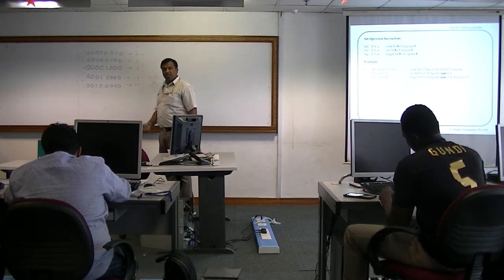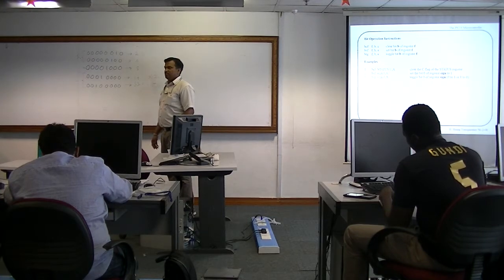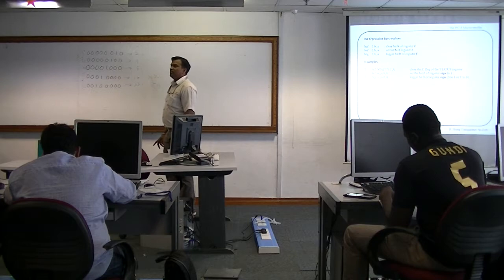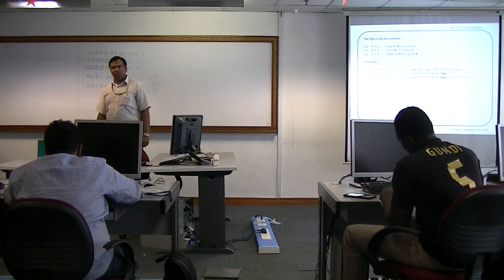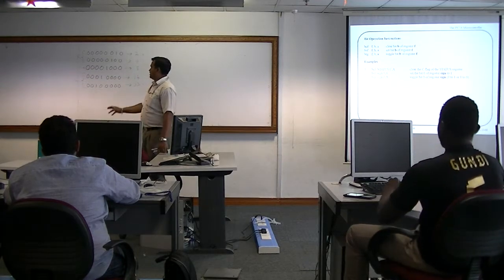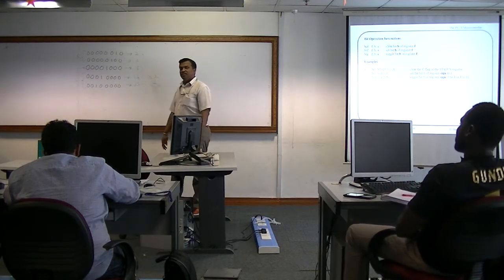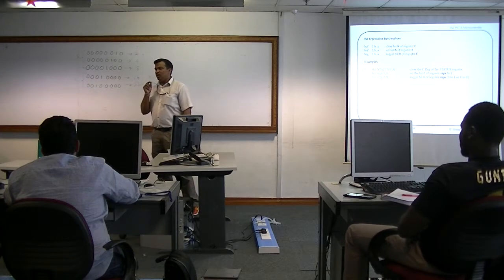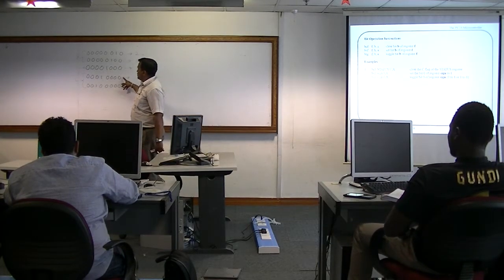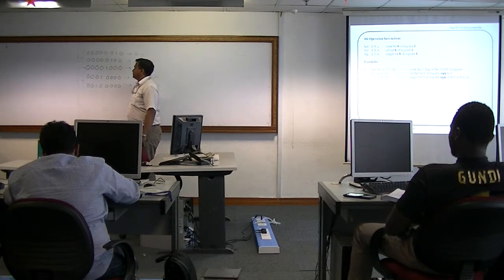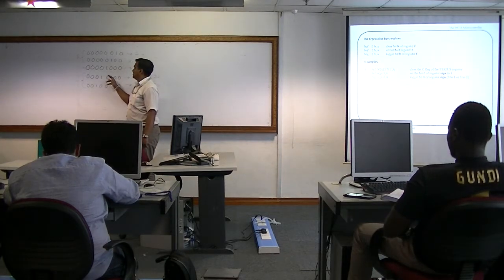So this is one of the applications of rotation. You can perform multiplication and also division without even using the multiplication instruction. Can you understand? Of course, I have given a simple example, but there are a few rules that you have to abide by. Whenever you want to perform multiplication, you notice that the most significant bit will enter here, right?